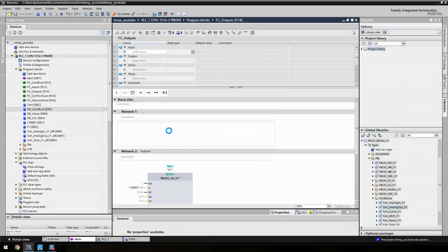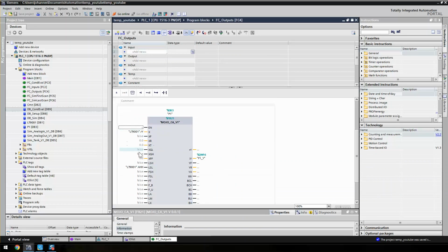Now let's use it. This CA is basically just a PID with different modes. So the feed forward we could use with this PID would be to feed forward the water level. We could then use the outflow now, which will be susceptible to noise since it's based on a measurement, or we could just use the reference. Since we know that if we're going to be at the 50% water level, we'll need some amount of flow, since that's what's going out of it.